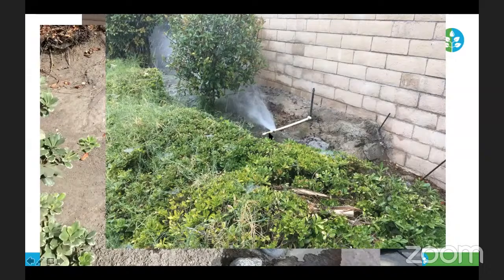Another issue here, so this is when the valve is running, so this isn't constantly under pressure. So when the valve's running, there's a massive leak. This actually was from an evaluation that we did, and I noticed before turning this on, again, this is in the very, very back of the property, but I noticed all this grass growing really, really high in the shrubbery. Weeds can be indicators of overwatering. So this has been leaking for a while.